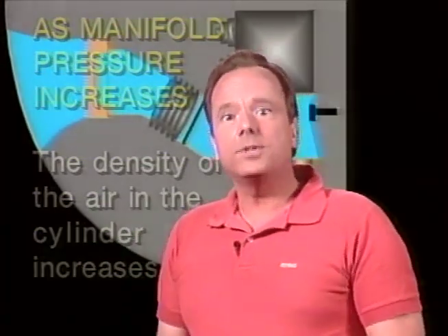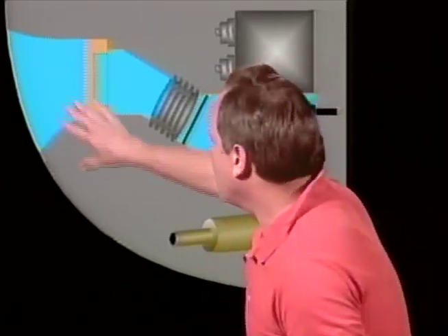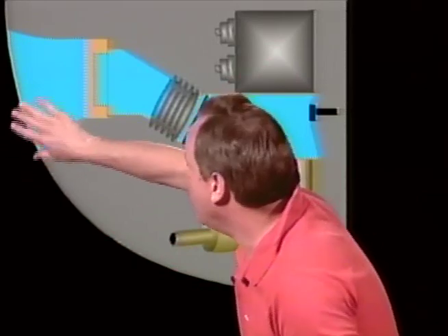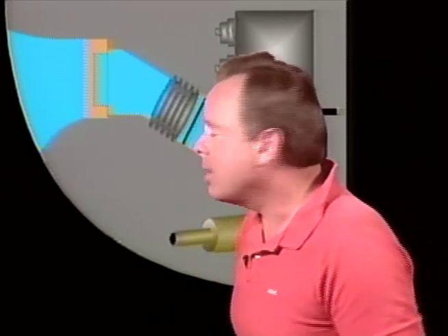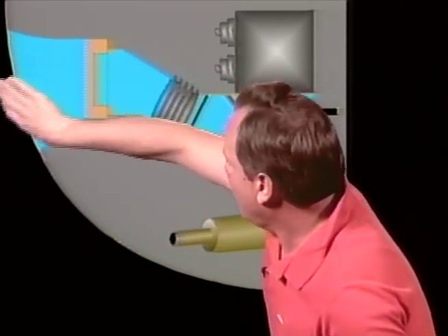They're also going to ask you, what's the action of the scoop at the very front of the engine here? They call it the air scoop, carburetor air scoop. Well, it's a real easy answer. The purpose of a carburetor air scoop is to supply air to the carburetor. But it may also increase the pressure of the incoming air by ram effect. In other words, on some airplanes, as the airplane goes through the air, it rams the air in the front of the intake system and increases the manifold pressure very cheaply and efficiently, kind of a cheap man's turbocharging. So the carburetor air scoop can supply air to the carburetor and provide ram effect.